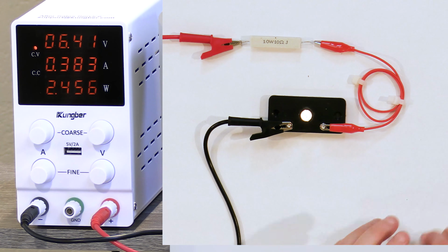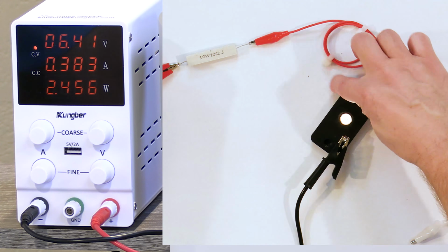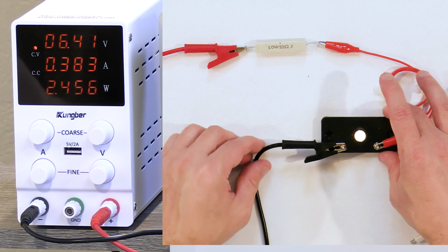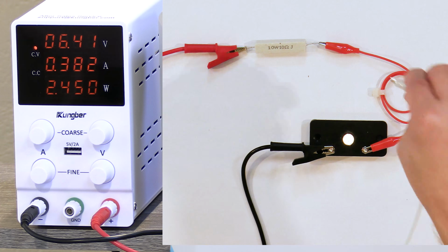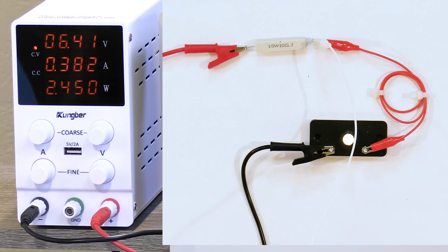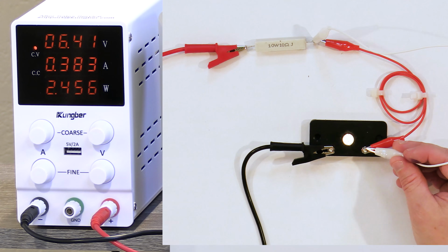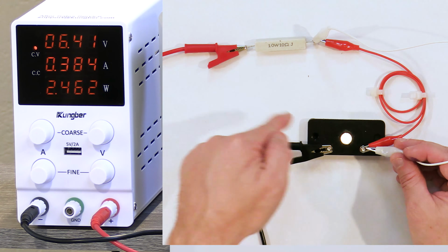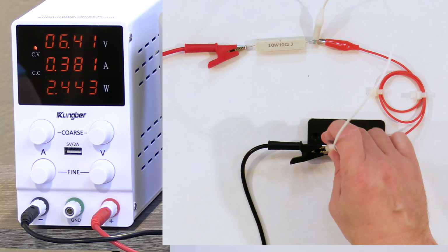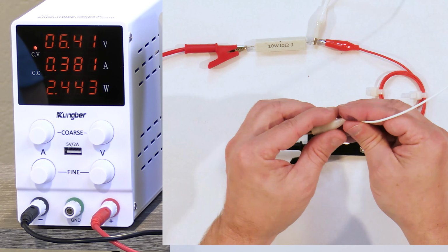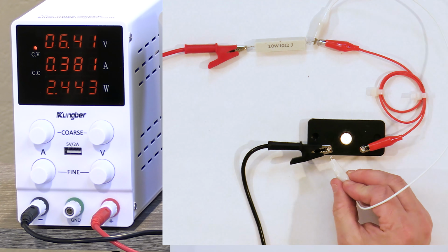We have a nice light bulb here. I'm going to try to arrange this in a similar way. I guess I'll just leave it the way it was over here. And if I connect a wire here, this is just a stray wire. If I connect it here, nothing's going to happen at all, because it's just like two parallel paths the electricity can go. But if I connect it here, all the electricity is going to go through the white wire and completely bypass the load. And let's see what happens when I touch it.